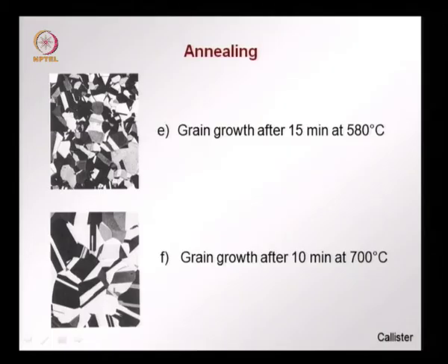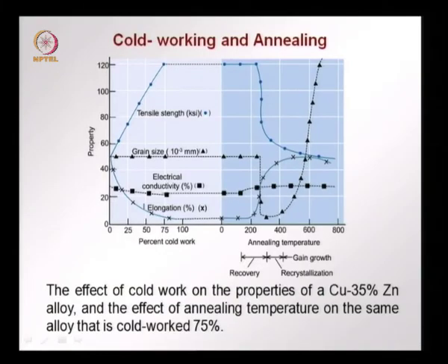Grain growth is significantly more. We have larger grains, fewer grain boundaries, and therefore we have a system with less potential energy or lattice energy. So these are the different stages of annealing. We can put both the phenomena that we have recently discussed together, cold working and annealing, in the same picture.